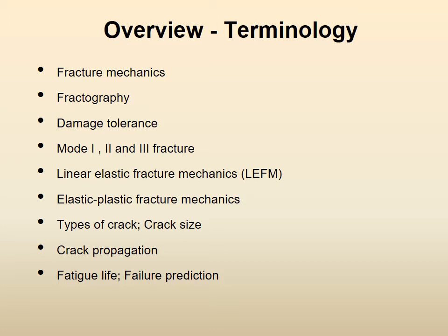The shafts and axles and camshaft and so on rotate, so there is a cyclic fatigue loading. But you have designed it in such a way that the maximum load, the load combined with the thermal load, right, is always below the design load. So can you then predict when fracture will happen, even though the load is always below the design load? So that is failure prediction.